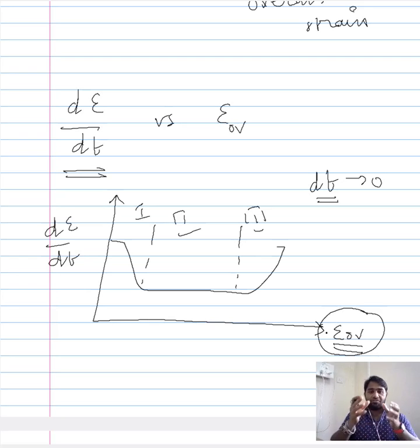As opposed to our previous consideration, we were able to arrive at this plot not from the initial conventional creep curve, but by looking into the instantaneous strain, the small strain exhibited by a material over a very small period of time dt. By relating that small strain to the overall strain, we arrived at this representation, which also reflects the creep behavior of the material. So in addition to the conventional representation of creep using strain and time, we can also represent the creep behavior in terms of the strain rate by considering the overall strain.